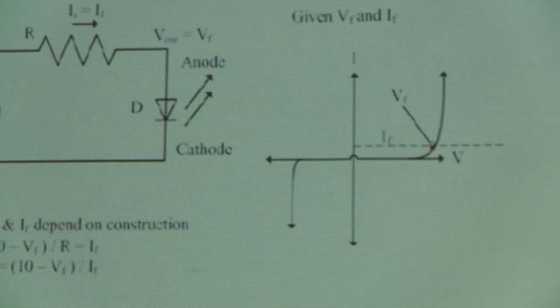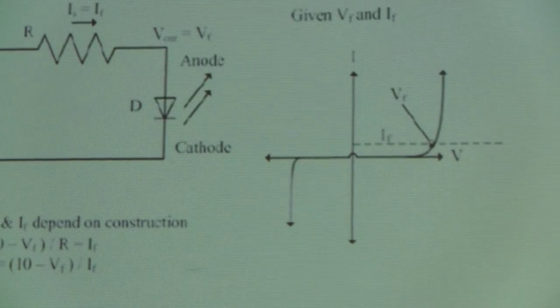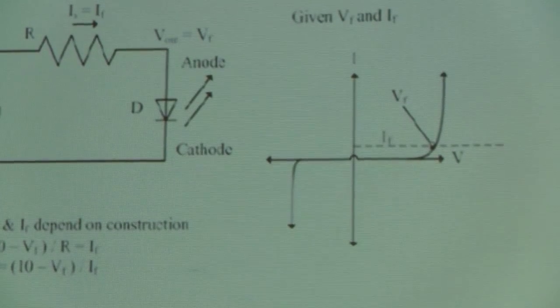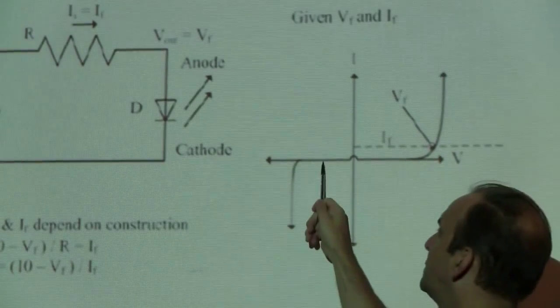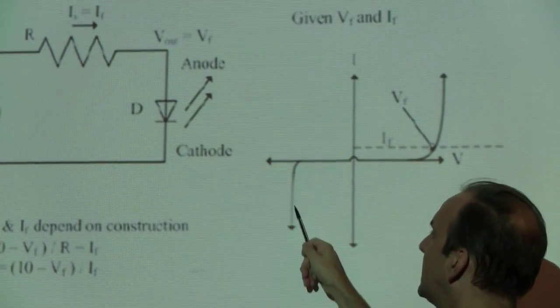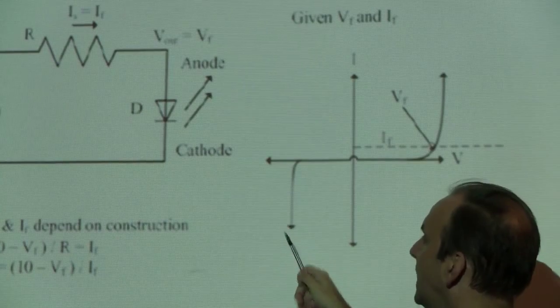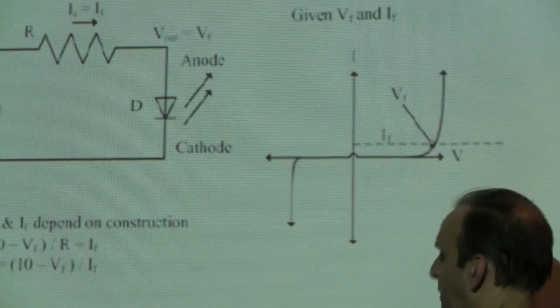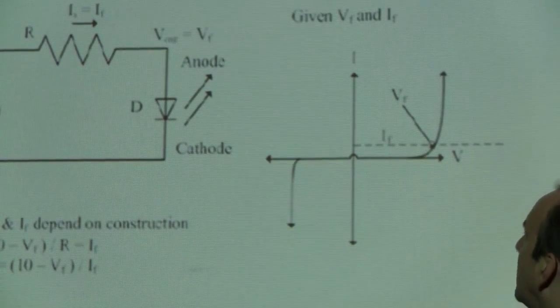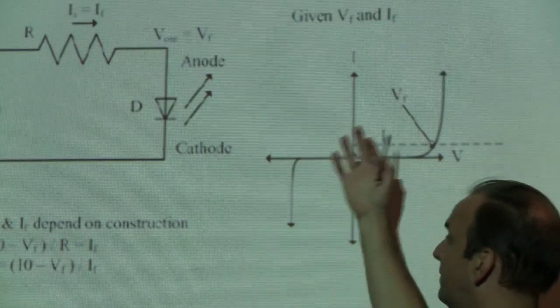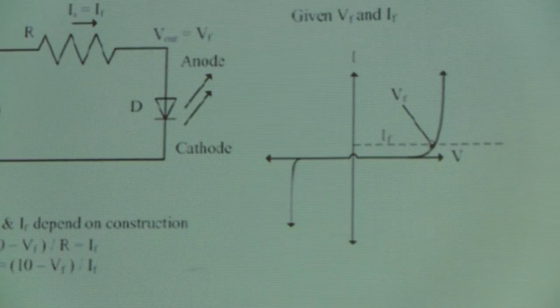And the reason why is it becomes a shunt. It's used in voltage regulation where you want to protect against over voltage. So if you start to drive it too hard, it really slams quickly and prevents whatever's attached to that point from seeing an over voltage. So it's just another feature of a diode that gets used.